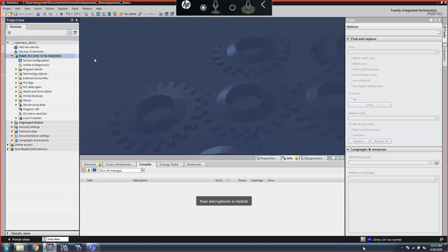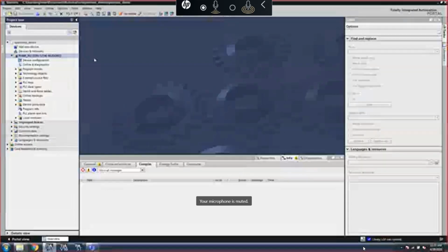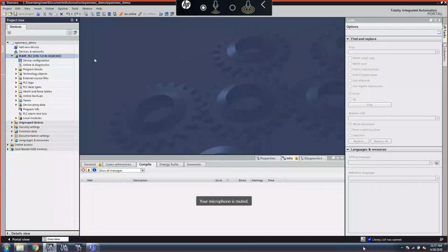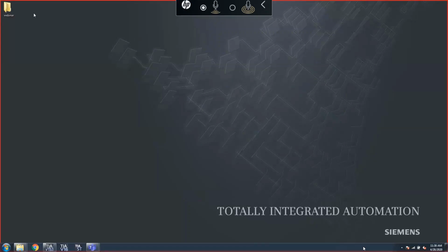Once you know that, if it is for 3 pumps, you know what hardware you need, and your blocks will be copied 3 times. If it is for 10 sets of pumps, you know the IO modules will be more, and the blocks will have to be copied multiple times. But right now, you are doing all these things manually. As I was saying, right from TIA portal version 14 onwards, we give you some open APIs, some DLL files to be more exact, which you could make use of in a program that you could develop.